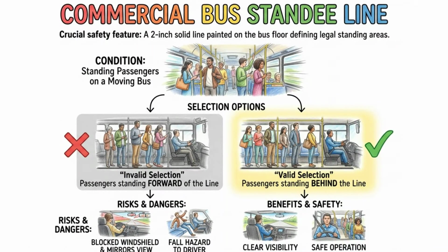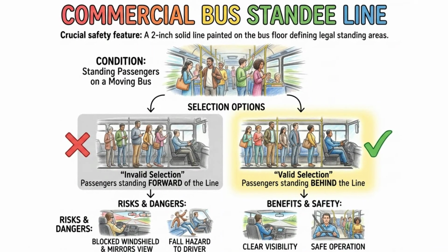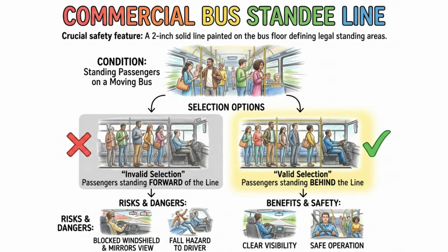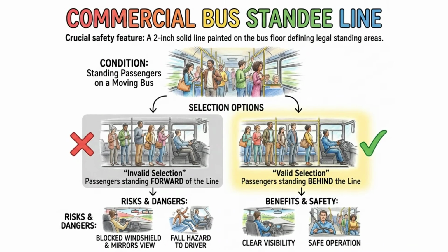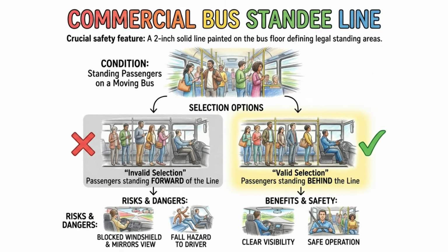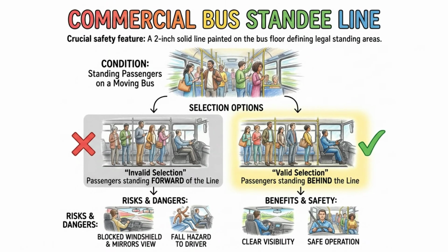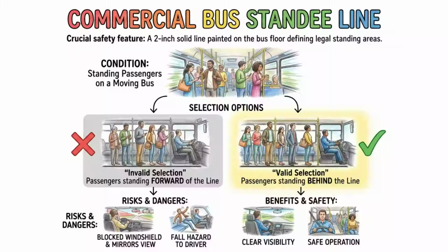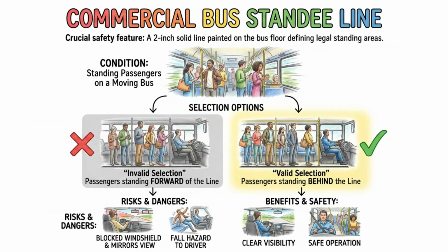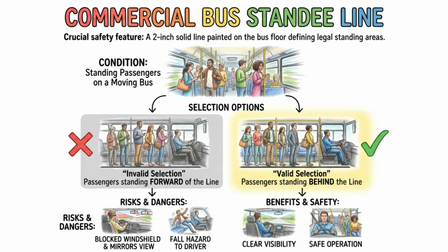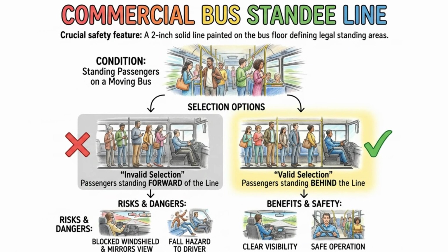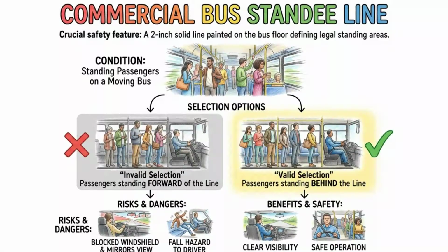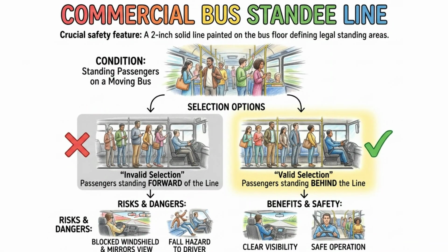The height of your cargo directly impacts your vehicle's center of gravity, which is a major factor in preventing rollovers. To keep your truck stable, you should always load the heaviest items as low as possible and centered from left to right inside the trailer. A high center of gravity means the truck will lean heavily to the outside when going around a curve, making it incredibly easy to tip over. When test questions mention a top-heavy load, your immediate thought should be the increased danger of a rollover accident, requiring you to take curves at extremely low speeds.